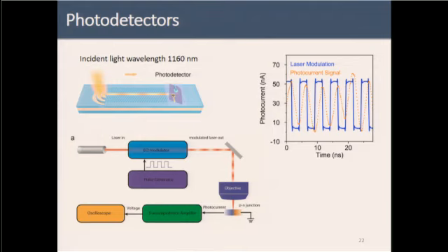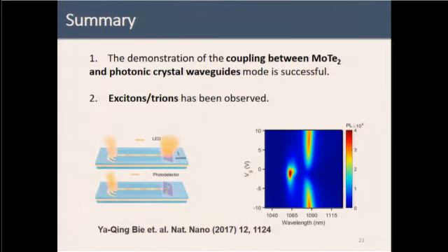In the end, we can observe it using an oscilloscope. As you can see, our device is not a DC device, but can work at very high speed. Here I'm showing that our device can work at 200 megahertz. This is quite nice, but it is not the real limit of our device. It was actually limited by our measurement: the impedance amplifier itself has a cutoff at 200 megahertz. In principle, these semiconductor devices could work as high as several gigahertz. That's our fundamental limit.